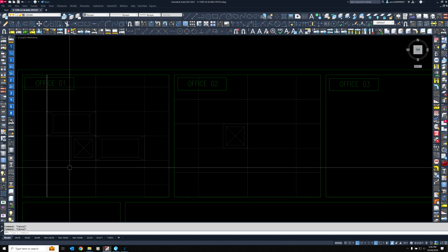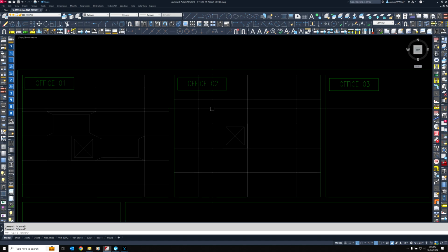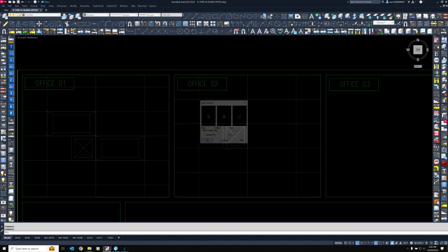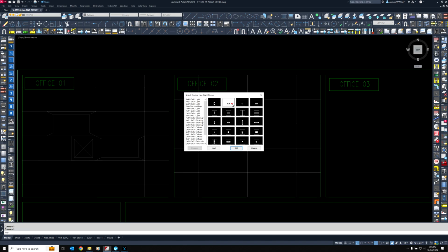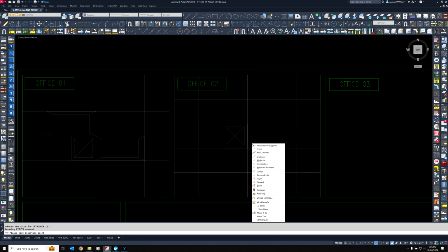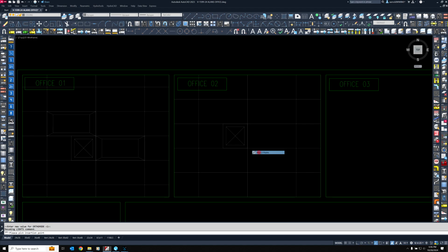The next thing we want to do is insert the lights in this tile and in this tile. So let's go back and select the light, outline 2x4, turn sideways, hit OK, and that's the quick shortcut to your endpoints, snap points. Hold down shift and right click. We're going to hit mid 2 points, and then it's going to ask you to pick those 2 points.